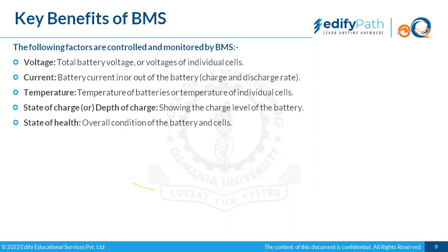And state of charge or depth of discharge. State of charge is how much charge the battery is holding at any point of time. That is SOC, as we call it. It would always show the rider, at every instant, the state of charge of the battery, because during the ride the voltage keeps changing, reducing with every kilometer we cover. So it would keep showing you the actual, instant charge or voltage that the battery is holding.